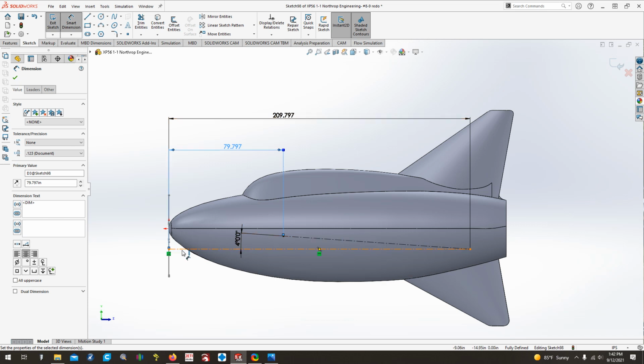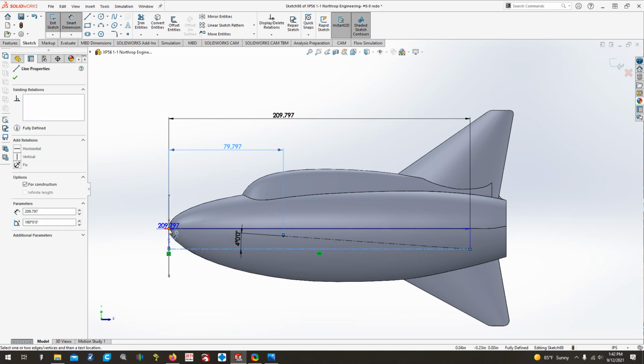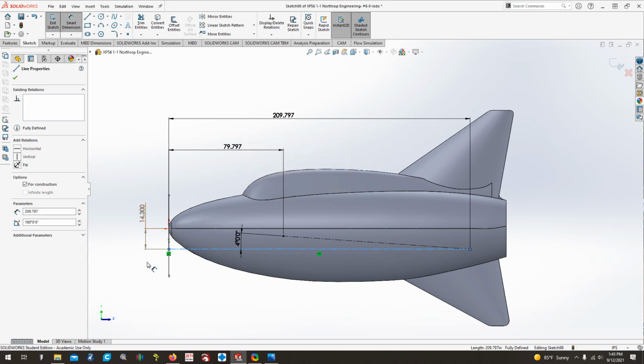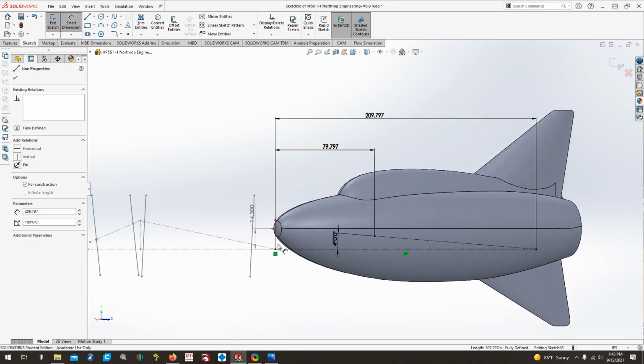And we also want to make sure that we verify that this plane here is exactly 14.3 inches below the crew nacelle reference plane, which is also the origin point that runs right through that point. So here we can see we have our 14.3, which is perfect because we knew we set this line here on the front master diagram at 14.3 inches below.